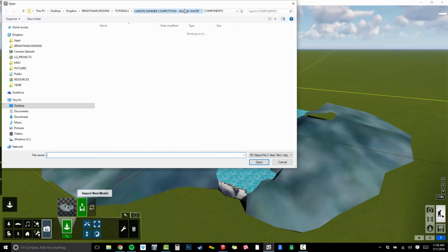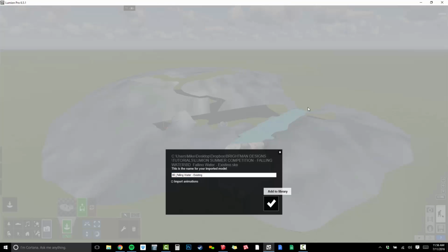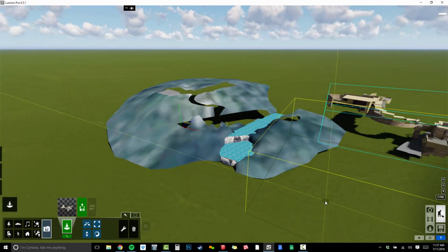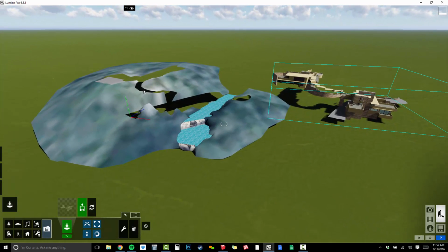So now we're going to import our existing conditions. I'll choose Open, say OK. Now this one, I'm just going to drop over here, and let's start to look at what we've got here. I want to make sure that I get my layering set, because oftentimes I don't pay attention to my current layer. It's a bad habit I've gotten into after working in SketchUp so long, where layer 0 is always active.